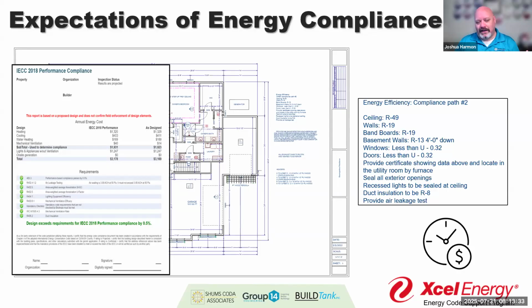I make this point a lot: in the 21 edition of the code, most of our energy considerations are on lighting, right? But you can make the argument in a performance rating system that by controlling those, prescriptively, all I have to do is have 100% high efficacy lamps and put in some dimmers, right? That's what the code says.